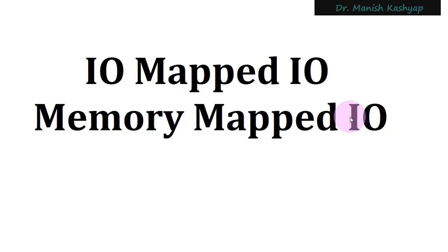And now coming to today's topic, we are talking about how to interface your input output devices with your microprocessor. In that context, I'm telling you that there are two ways in which it is done. First is called input output mapped input output, and the second one is called memory mapped input output. What do they mean? If an input output device is connected to locations which are not memory locations, I mean, in 8085 we all know that there is a possibility of attaching 64 kilobytes of memory at max, right? You could use lower memory than that, and you could use the full 64 kilobyte memory.